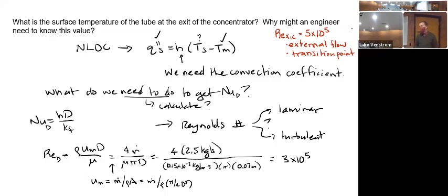We're asking a different question. So all that's 100% true, but we can't use that to interpret this Reynolds number, which is based off of the tube diameter. It's not a Reynolds number based off of some position away from the leading edge of a flat plate. It's kind of a different beast. So I totally get it, but this isn't the number we're going to use.